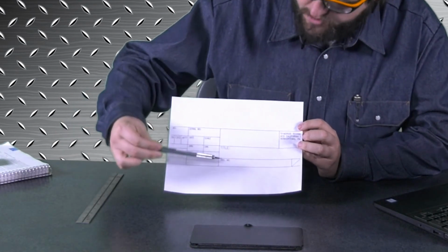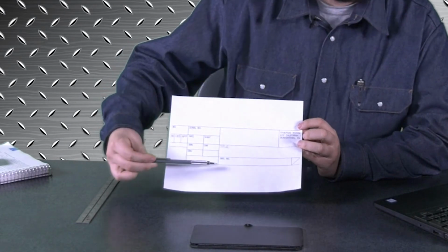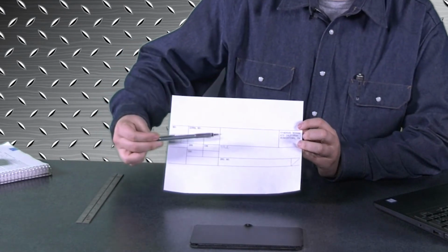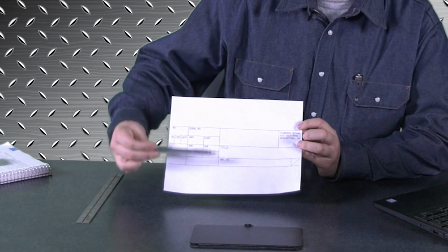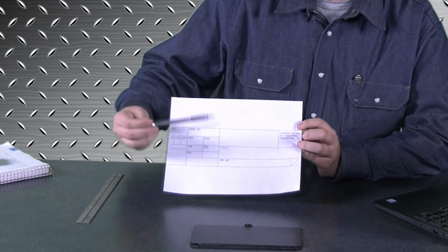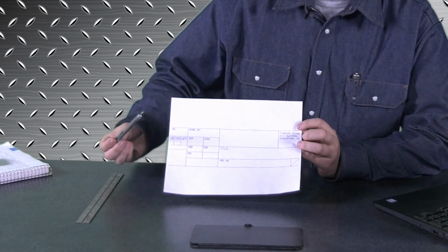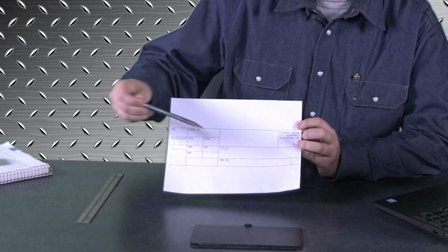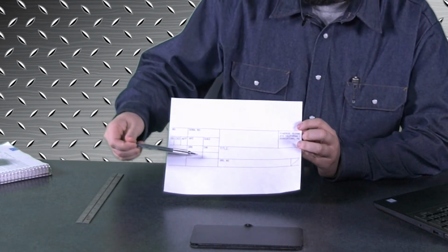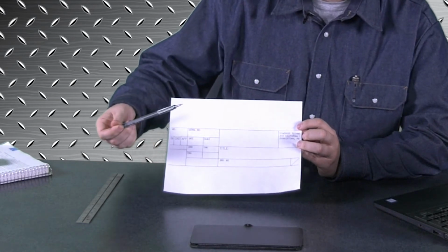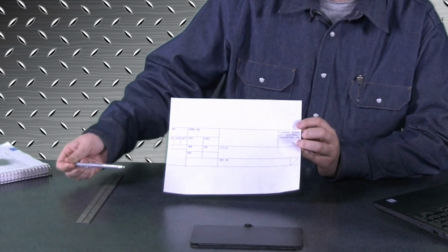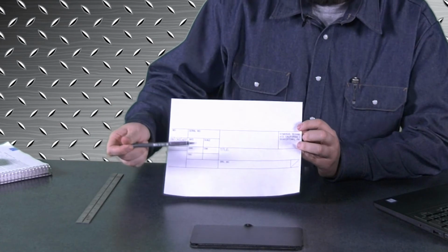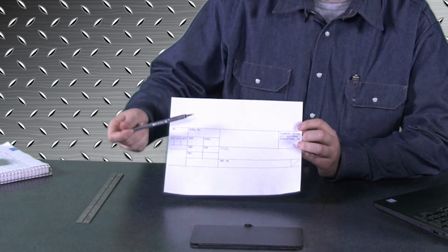Now the next part you need to check is the drawing number, and you can't see it on here, but usually there's a drawing number and a revision number as well. You need to make sure you are using the current revision. You could be on revision C, you could be on revision D. If they ask you to build a part and your print says revision number A instead of your work order saying revision number C, you know you've got the wrong print or the wrong revision of that print.